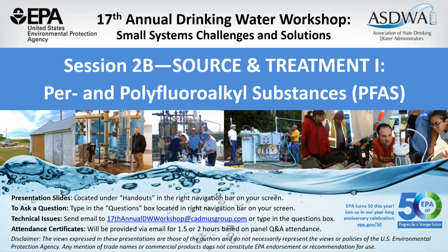Yeah, definitely we saw a range, not only for the PFAS compounds, but for the other CECs we looked at. The ones that are wastewater derived, especially if they're well linked to the wastewater treatment plant and close in proximity, you might have increases. Just the hydrograph coming out of the wastewater treatment plant fluctuates during the day based on the morning flush coming through, that type of thing.